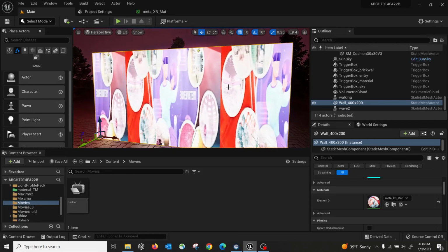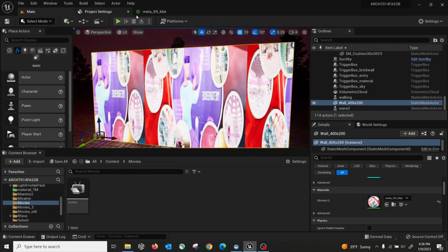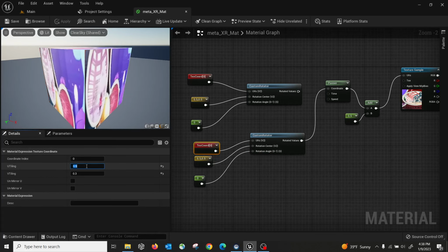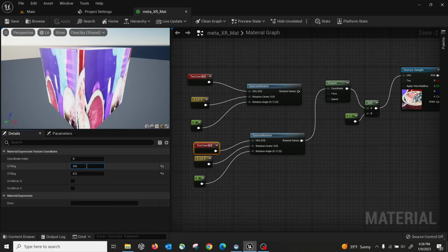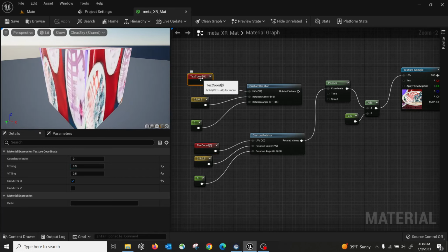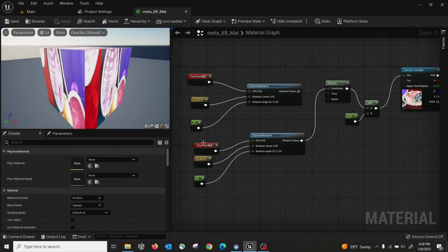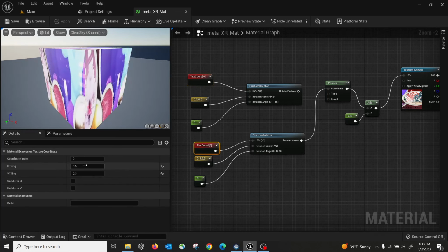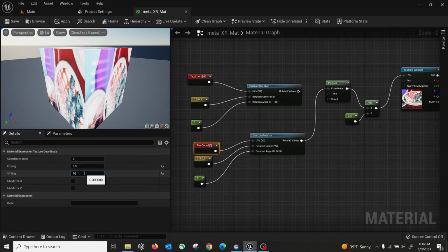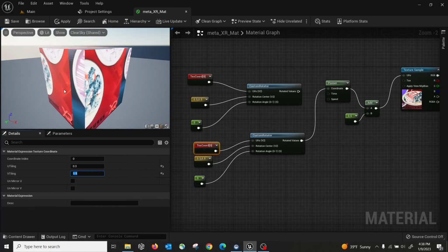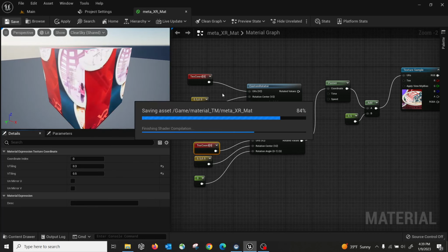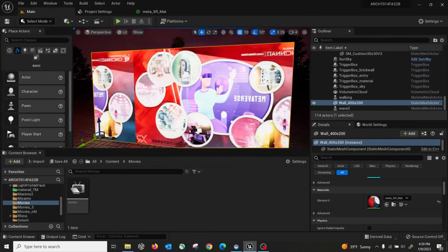So if you do want to squeeze this a little bit shorter, right, you have to go back here and play with the UV values. I don't know, maybe this should be a little bit larger. If I go back to my original one, I use 3 and 5 instead of 5 and 3. So 3, 5. Yeah, the proportion of the original image. Right, that looks much better.